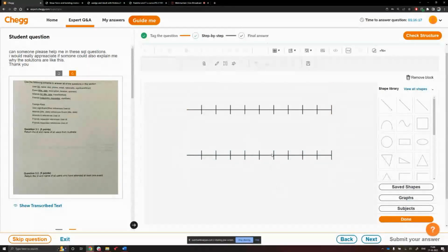To make some changes to it, you can click on ungroup, and then you can again ungroup, and then again ungroup. You have to ungroup in the same order as we grouped them. Then you can access every individual point and make the following adjustments.